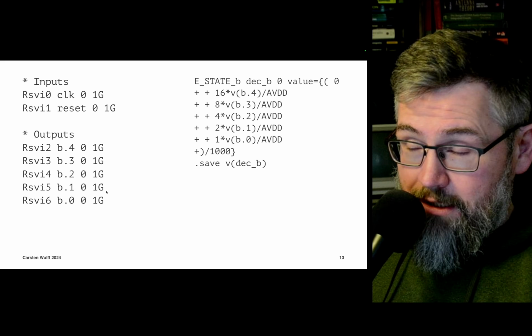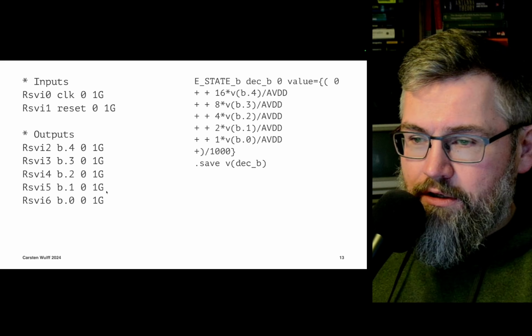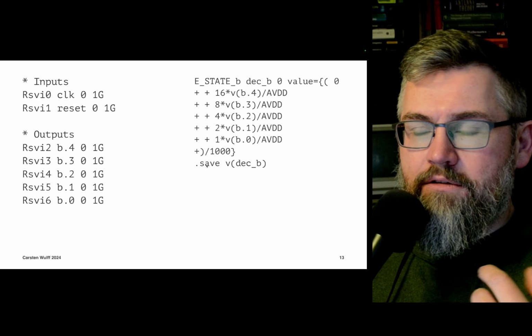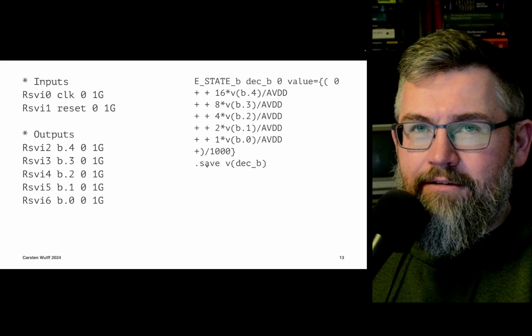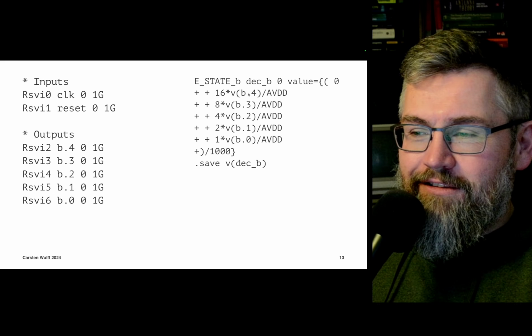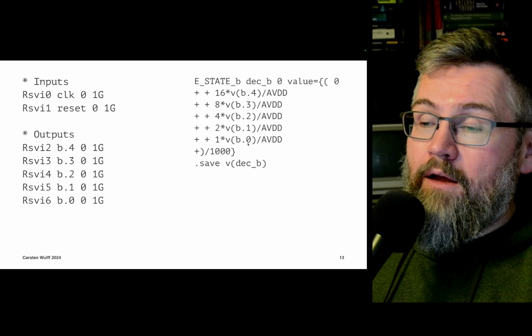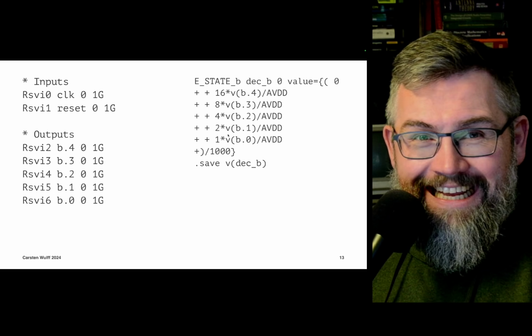This would add some leakage current, so if you're operating your circuit in nanoamps, you have to change this value yourself. And then, since it's a pain to look at the digital output signals in my waveform viewer, I combine them into a bus.